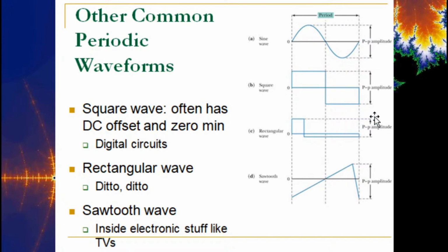So it goes back high for 10% of the time and then it's off for 90% of the time, right? High for 10% of the time, off for 90. That is still a periodic repeating signal, okay? It's just that the frequency is different. All right, the frequency is still how long it takes to complete one cycle, but you can't go right into the middle of it and have it be on for half the time, off half the time. That is a straight square wave signal.